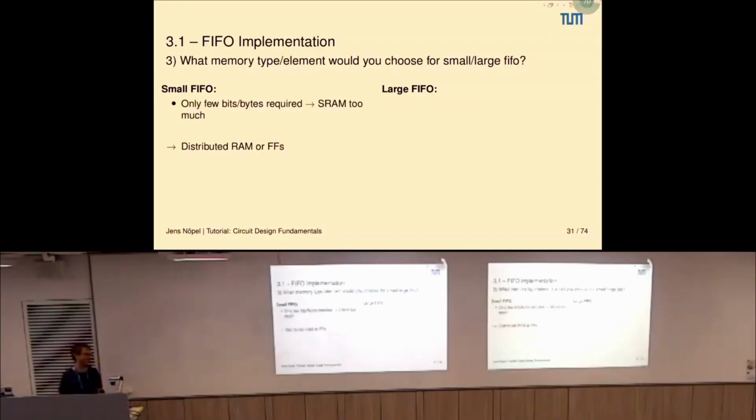It's exactly the other way around. Yeah, it's all right. But why is that? A flip-flop is very suitable if you have just a few bits or bytes, because SRAM is, let's call it, too much, because SRAM usually comes, as I said before, in larger arrays.